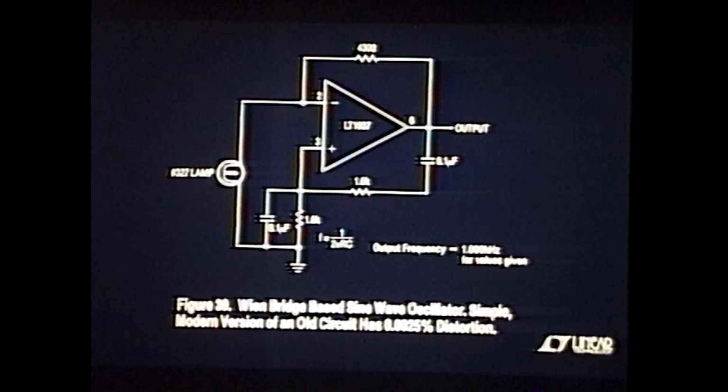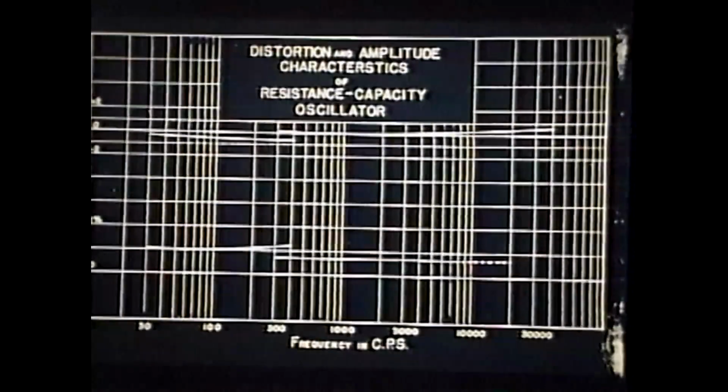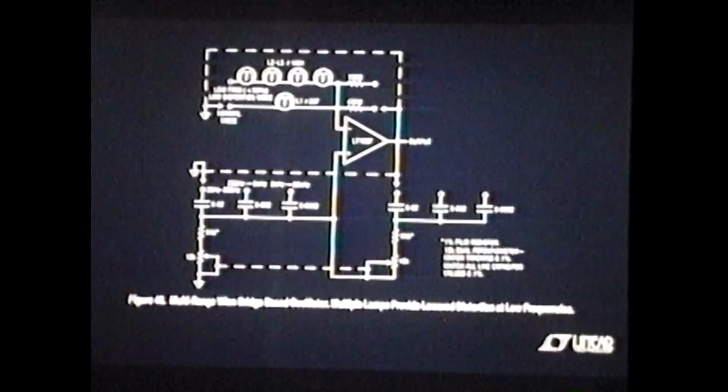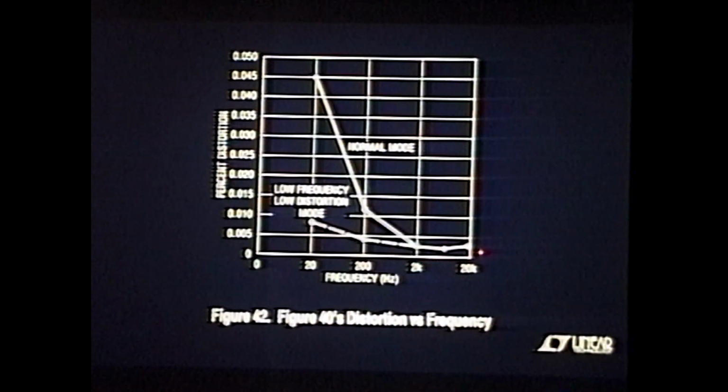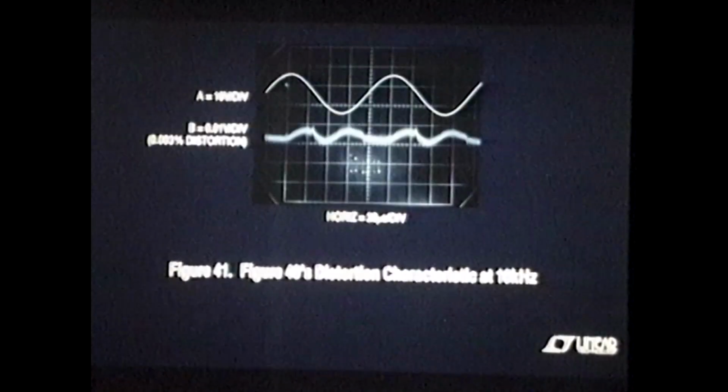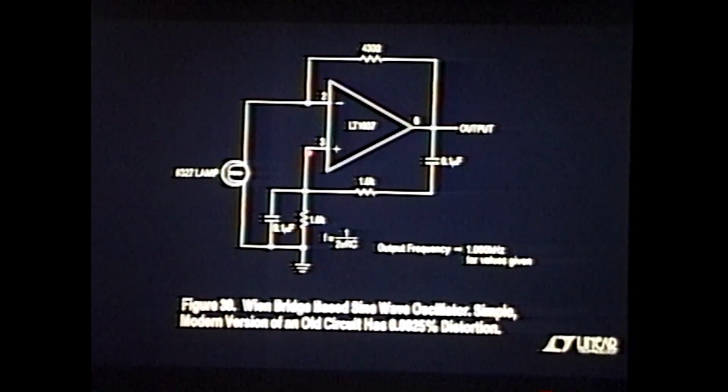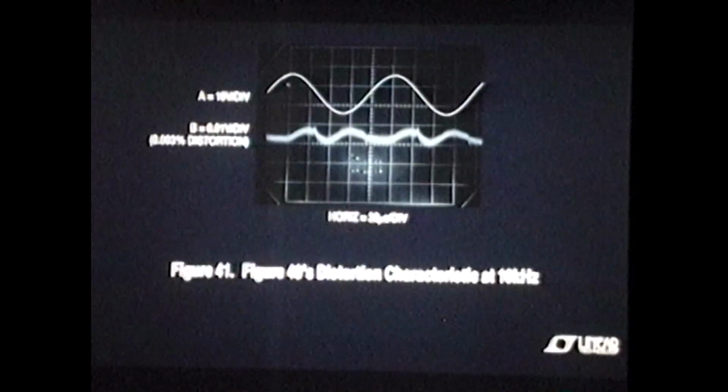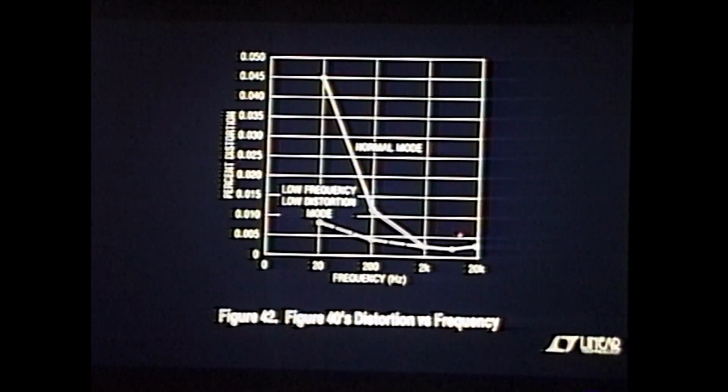You're asking a lot. This thing's moving at multi-kilohertz, and then the real clue, if I can find it, remember I said this plot was interesting because of this? I'm also saying there's a lot of common mode swing at the inputs here. And I'm chasing an effect that seems to increase with frequency.